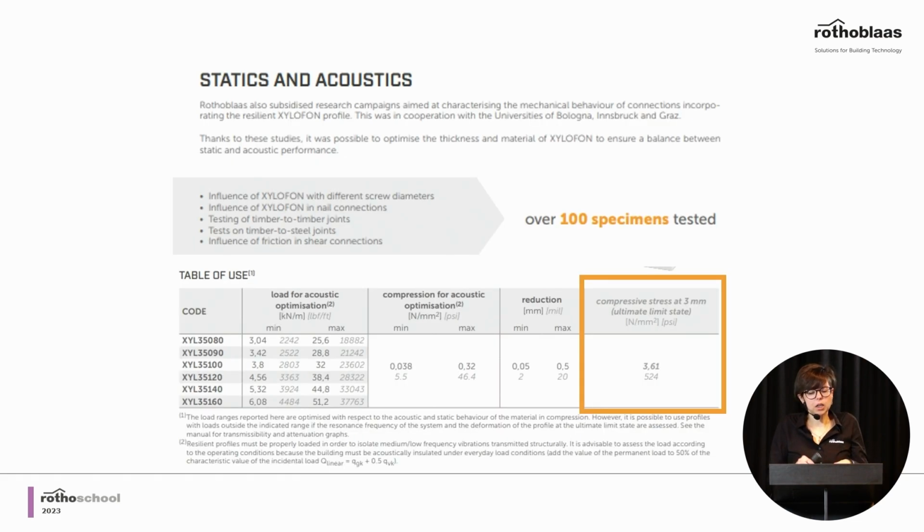But important to know is that resilient interlayers are inside the structure, so we cannot just consider the acoustic performance, which is quite high, but we need to consider that the material needs to be designed to be inside the structures. This is why with Rothoblaas we have done many static tests in order to understand what happens to the fastening system if we have a resilient interlayer between the joints.